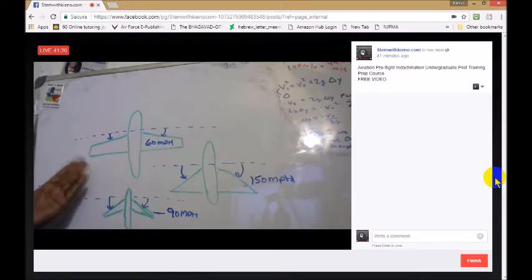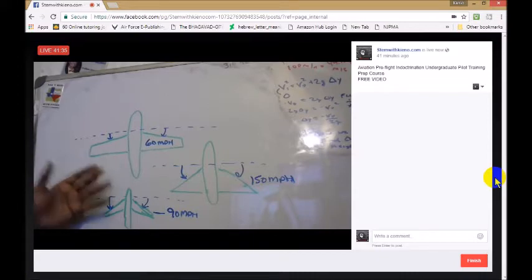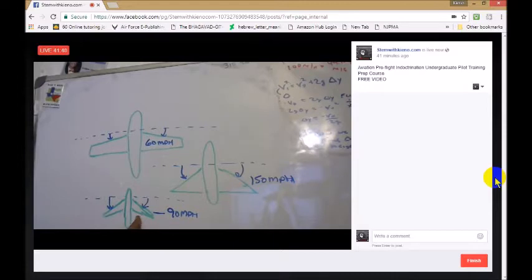If it's something like a Cessna 172 or a Piper Malibu, or a Cessna Citation, which is a jet but has a straight wing configuration, it can land on very, very short runways, where these two aircraft cannot. This is kind of like your airliner configuration here. This aircraft is not going to land on a 1,500-foot runway because it has to come in very, very fast in order to produce effective lift. Same with this one.